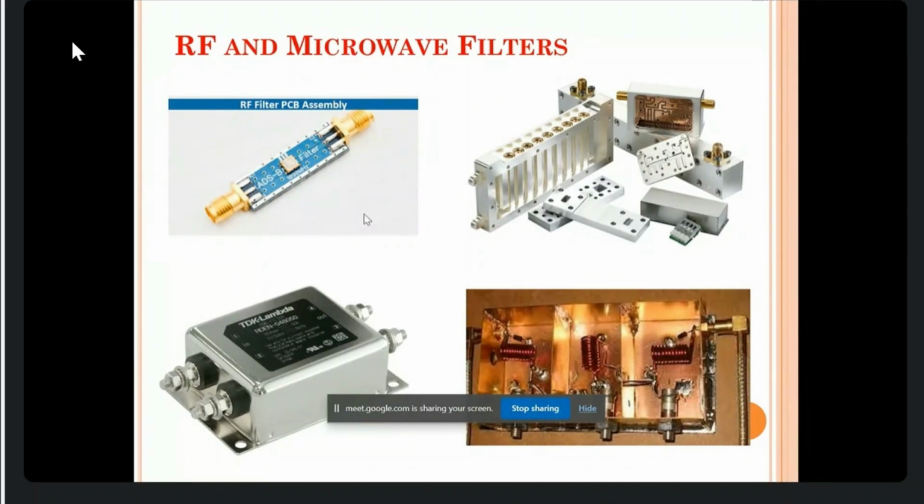We have to close it like this, because of shielding and to avoid interference, since we are going to operate at higher frequencies. And also we have to use specialized connectors. Every connector should work at that operating frequency and support that bandwidth. Even every single pin, single hole and grounding, you have to take care of while designing high frequency filters.